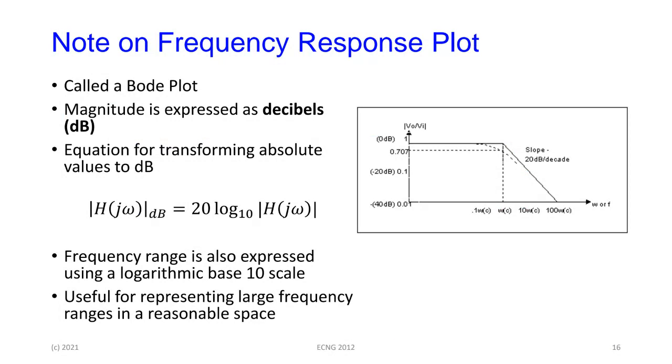You probably covered this elsewhere. I'm not too sure, but if so, it's a nice revision. But everybody following? Yeah, no, maybe. All right? So all single pole first order transfer functions will decrease at 20 decibels per decade. And we're going to see how to plot that without even plotting frequencies when we do Bode plots in signals.